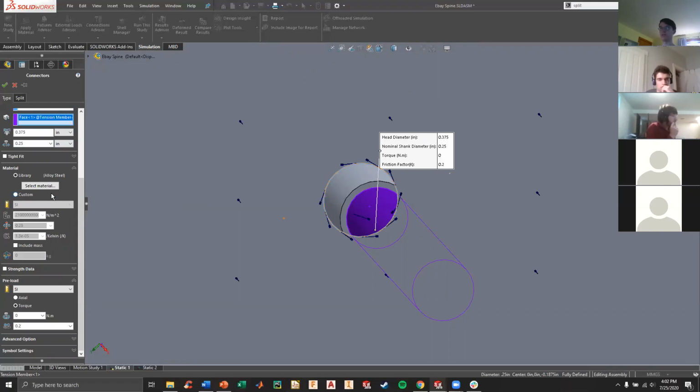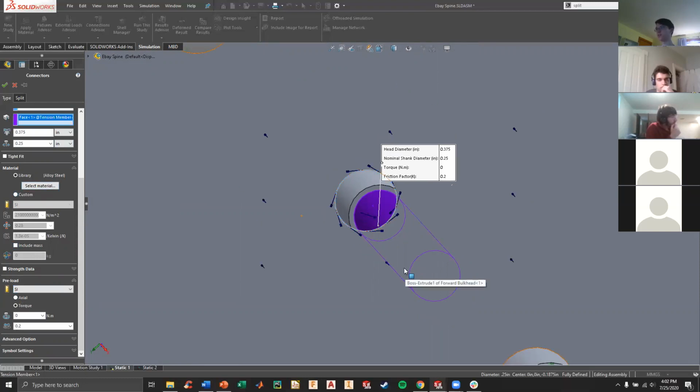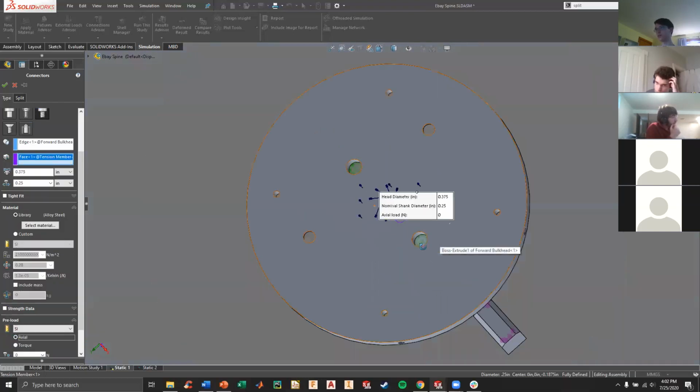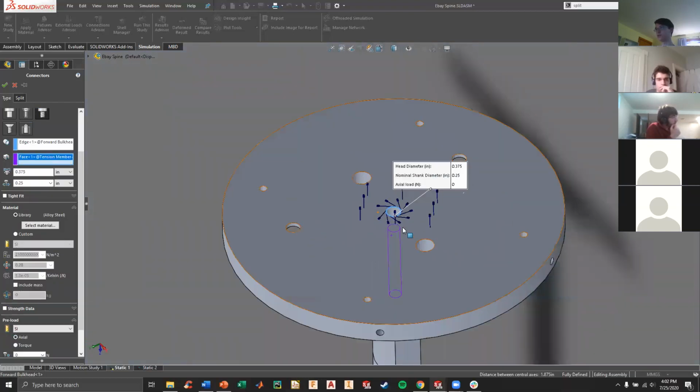Some of the numbers that McMaster has on their website seem a little bit high, but I guess they kind of make sense. They're certainly higher than the alloy steel material SolidWorks has defined, but we're not too worried about it here. We're not anywhere near the area where the bolt is going to be the thing that actually gets broken. This is aluminum, so the aluminum is going to deform well before the actual bolt would run into any issues.